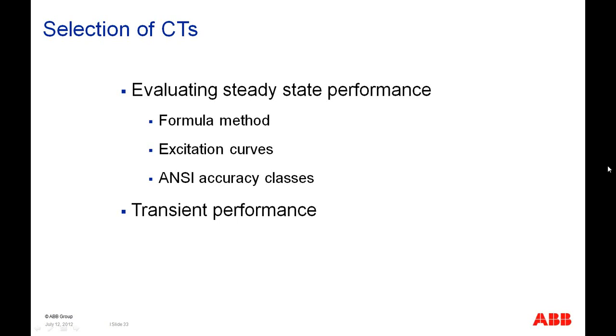A question came up about potential transformers. I never got to visit because this was so small here. But someone asked a question: can the PT be used for both relaying and supplying power as long as the burden stays below the kVA rating, or must it be used for one or the other but not both? Actually, there were some PTs that were called power PTs that were used for supplying both metering and power to stations for a while. But typically you tend to separate those two and just use a separate auxiliary power source for the power for the station and use a separate electrical transformer. But some have been used for both.